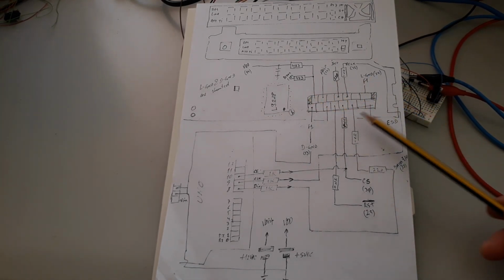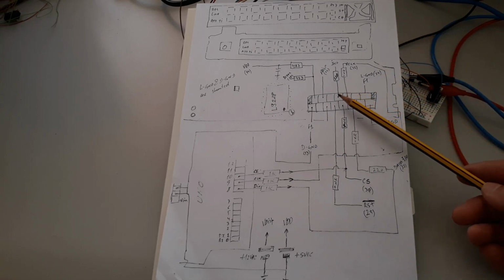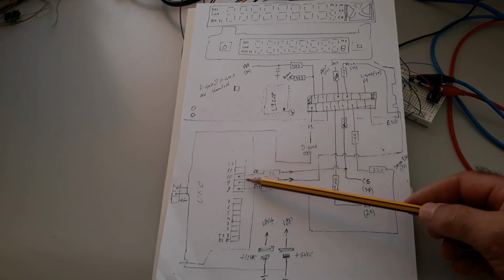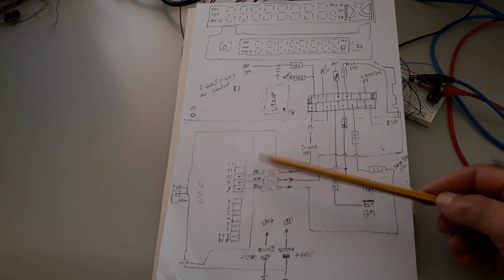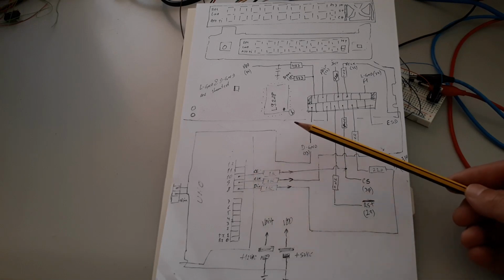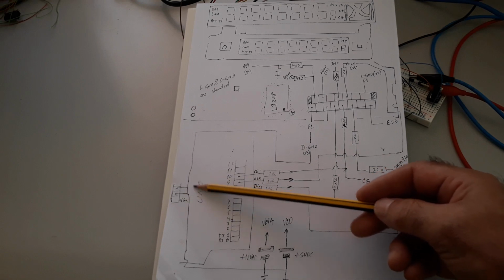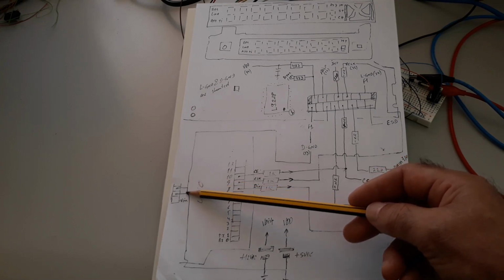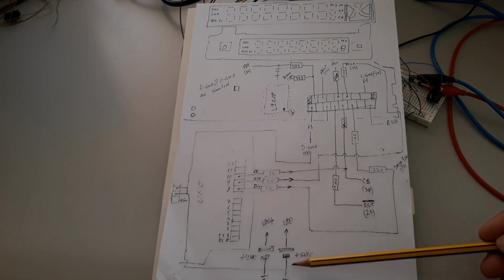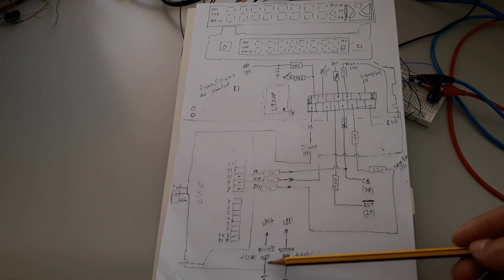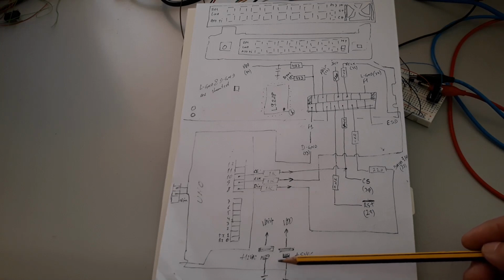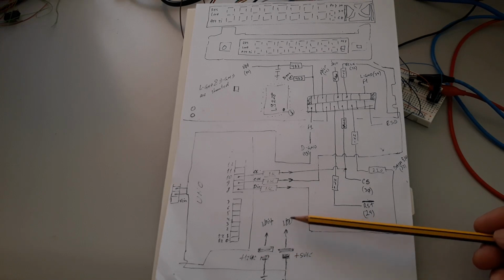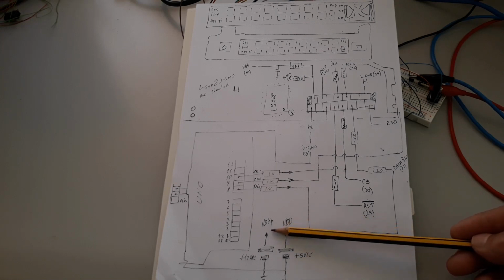The pins to connect the panel are present in this block. You can see the connection from the Arduino, pins 8, 9, 10: data, clock, chip enable. At this point you have the GND. This is very important: you must keep this reference connected to both power sources, the GND from both powers, the 5 volts logic and the voltage to the segments.